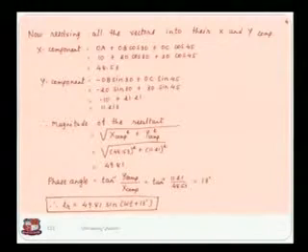OA, OB and OC is nothing but the magnitude of the current which is given in the data. So OA is equal to 10, OB is equal to 20, and OC is equal to 30. So our equation is like this: it is equal to 10 plus 20 cos 30 plus 30 cos 45. So your final answer is equal to 48.53. So it will give you the value of x component for all the 3 currents.